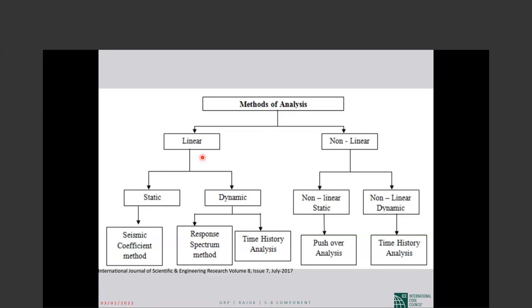The conditions, as we will see later, give us the m value for IO, m value for LS, m value for CP. It means the amount of damage that is acceptable in these deformation control parameters at the IO, LS, or CP level.